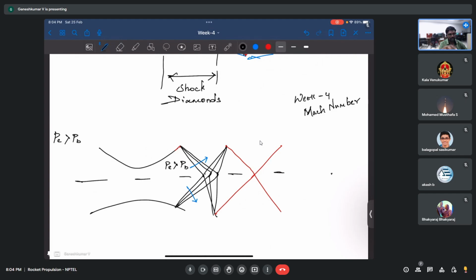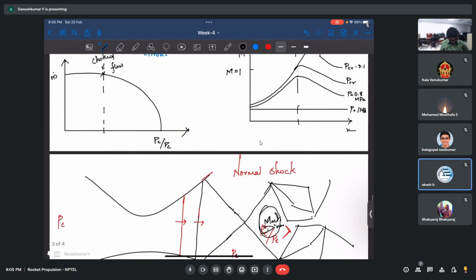So whenever you do not need a supersonic flow, and your Mach number at the throat is going to be less than 1, it is beneficial not to put a divergent section there, because if you put a divergent section, the subsonic flow velocity is going to decrease, and you do not want that. That could be the thing the professor must have mentioned, but I will look into it and come back to you. Okay, sir. Thank you.